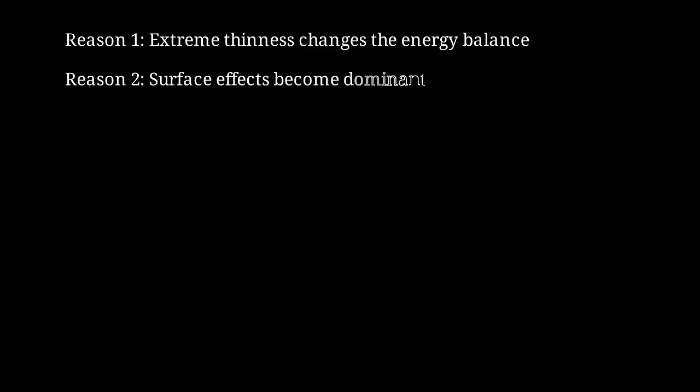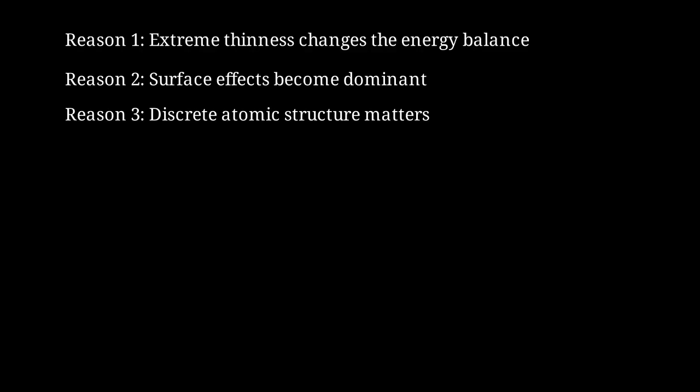Second, surface effects become dominant. At the nanoscale, surface energy and surface stress can be comparable to bulk elastic energy. Classical theory ignores these surface contributions. Third, the discrete atomic structure matters. When you're only 10 or 20 atoms thick, you can't treat the material as a continuous medium. Quantum mechanical effects and atomic scale rearrangements become important.